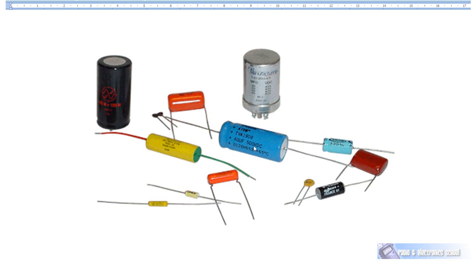Capacitors have to be given a voltage rating as well as a capacitance rating, because the dielectric can only withstand so much electrical pressure, so much voltage. If we were to put more than 500 volts DC onto this 40 microfarad capacitor, the dielectric would break down and conduct, and the capacitor would explode.